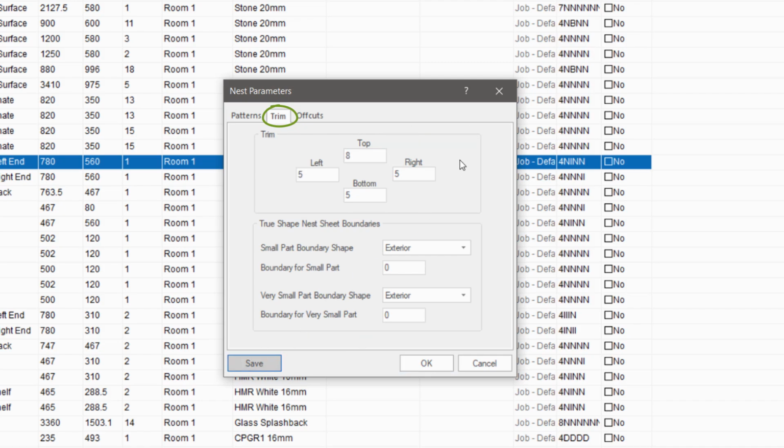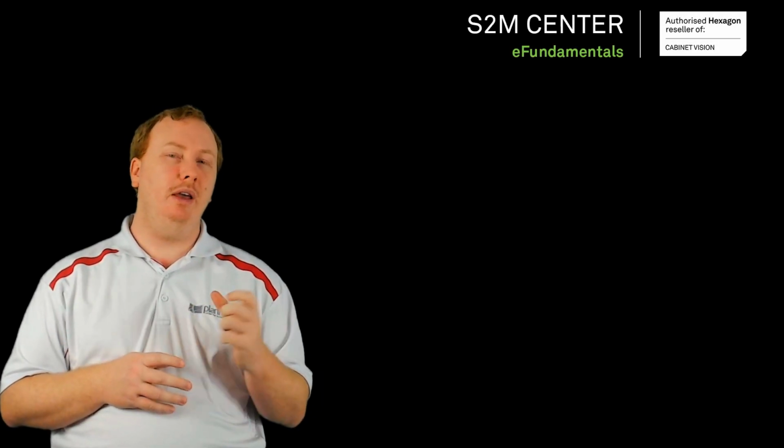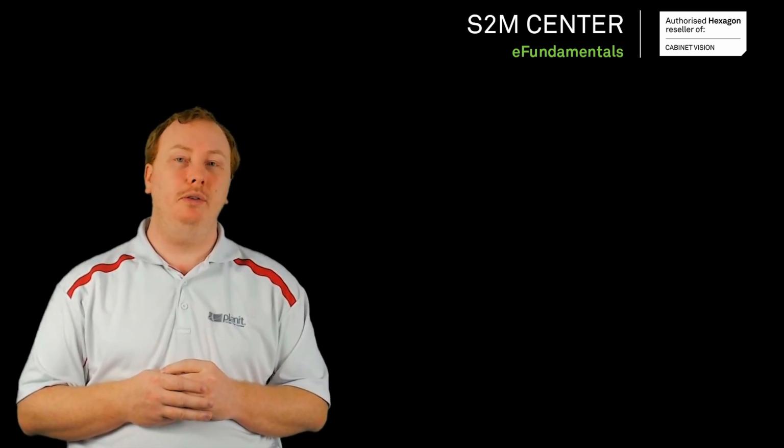On top of this, you could also increase a trim for a one-off run if you had a pack of boards, say, that had been damaged on one edge. For example, some water damage, or it had been hit by a forklift. Increasing it without hitting save means we can run the nest with a greater trim size along that one edge and utilize this to save some material. So go back through those options, change what you need to change, making sure to hit that save button as you do. Once you've done that, jump on across to your first S2M quiz.